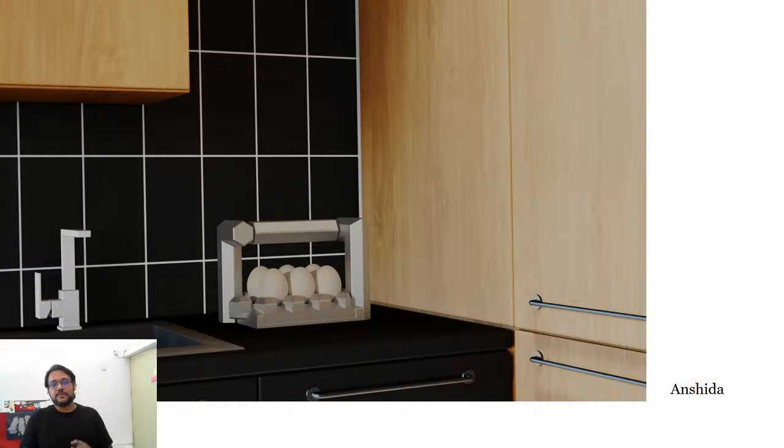So this was done by Anshida, and first of all, good effort. Okay, you've modeled the whole thing in Fusion, and you made the renders, and it looks fairly good. But the problem is, it's not a design which you can manufacture by machining method. See, one of the requirements of the assignment was you could make the whole design with just methods of machining. Okay, so with just the methods that we discussed in the class last time. So here, for example, if you can see my mouse pointer, this kind of an angle, right? Getting this kind of an angle is not possible directly. I mean, you would have to have some kind of joinery here.